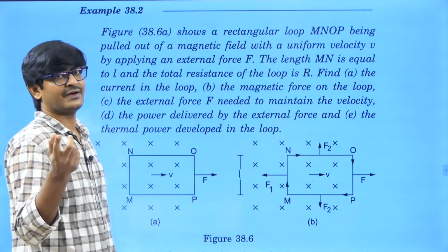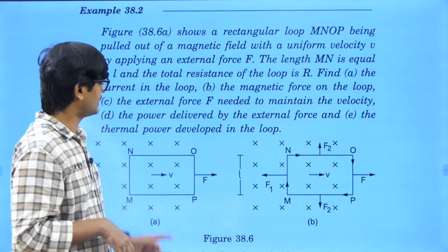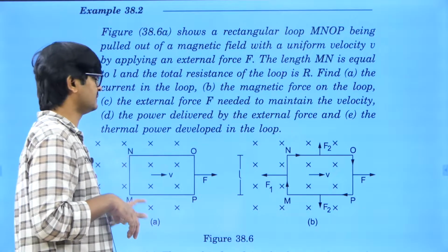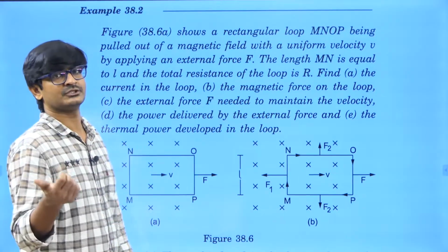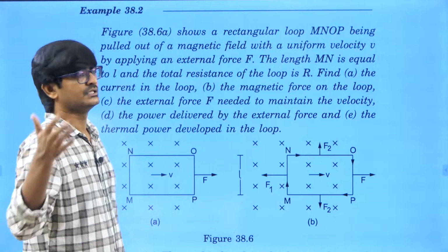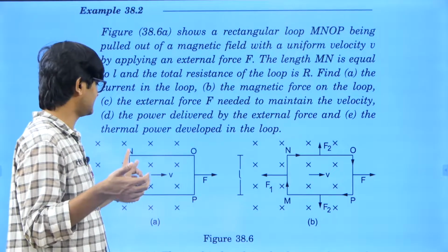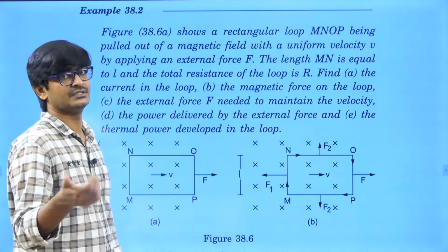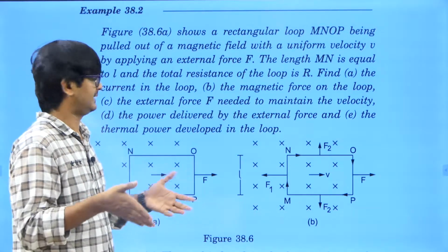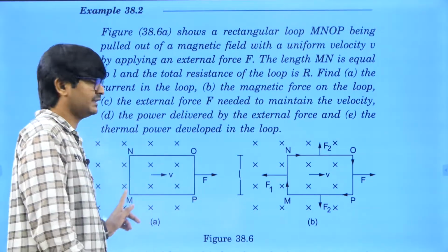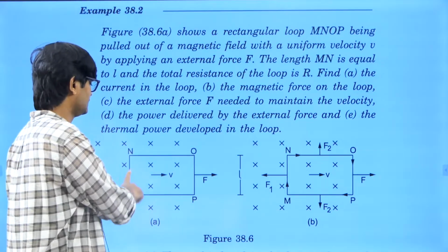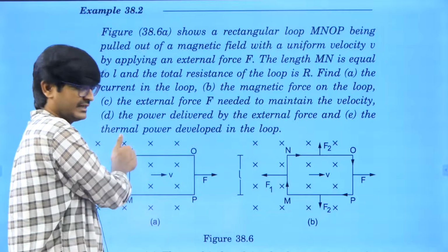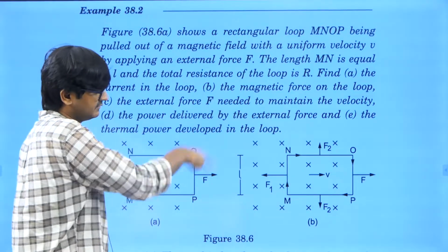Now by using Faraday's law, you can say what the induced EMF is, but you can't say where the induced EMF is happening. Faraday's law gives the total induced EMF in the loop, but going with the reason, motional EMF, we can see it will be generated here. So Faraday's law says what the induced EMF is in the total loop, but by knowing the reason, we can find even the location, right? So induced EMF will be here. How much will it be? (v × B) · L. So it will try to push the current this way, right?